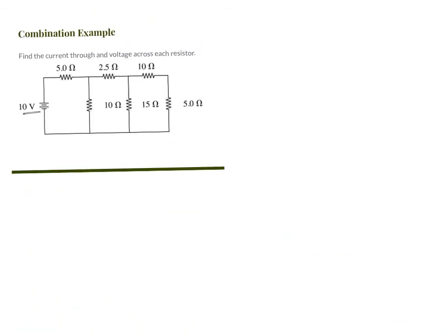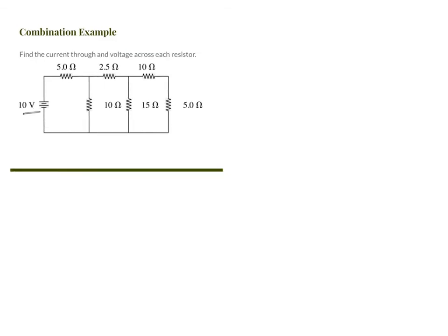So one thing that I like to do that we haven't done yet, that's kind of weird, is I like to draw my circuits, redraw them from the diagram in kind of a straight line. Because here, for me, maybe it's different for you, but for me, it's hard to tell what's in series and what's in parallel, and to get it all correct.